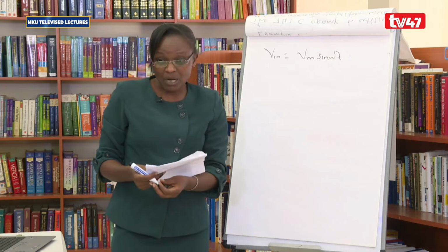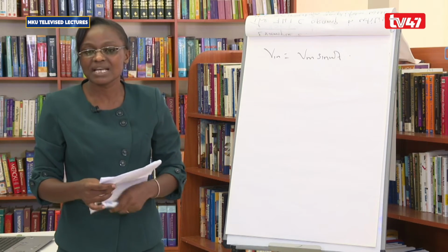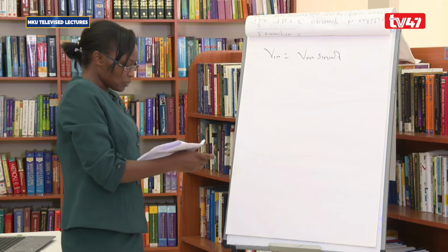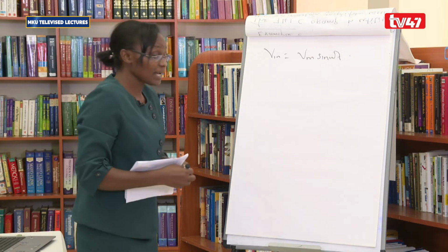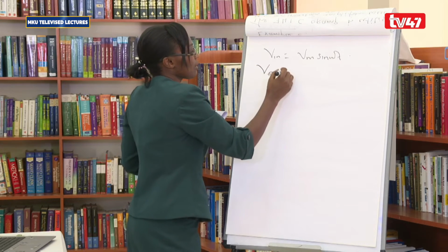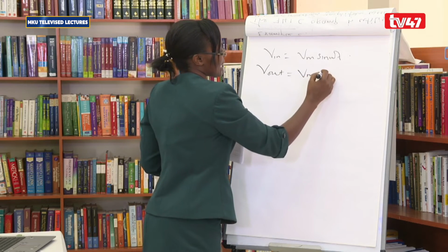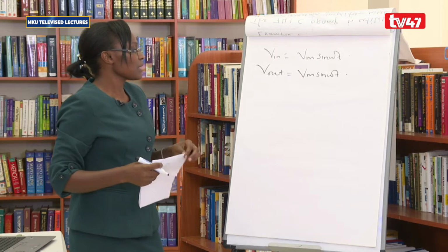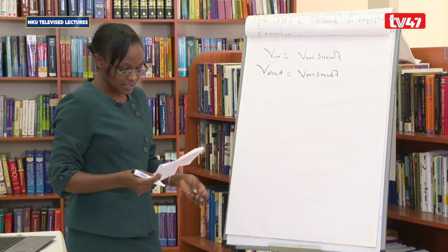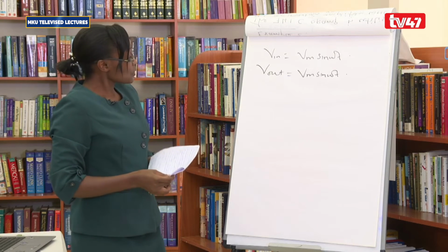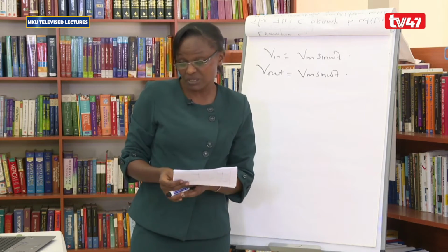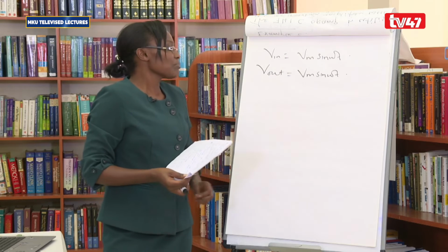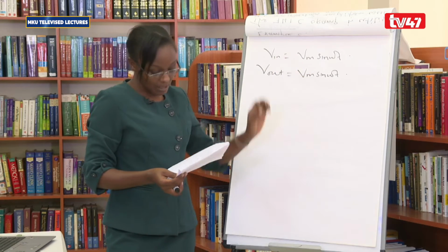And because we are talking about a unity follower, which does not have voltage gain, or rather Vin is equal to Vout, our output voltage will be expressed in a similar manner, such that Vout will also be equal to Vm sine omega t. So with no slew rate limitations, we are saying the output will be expressed as the same as the input.